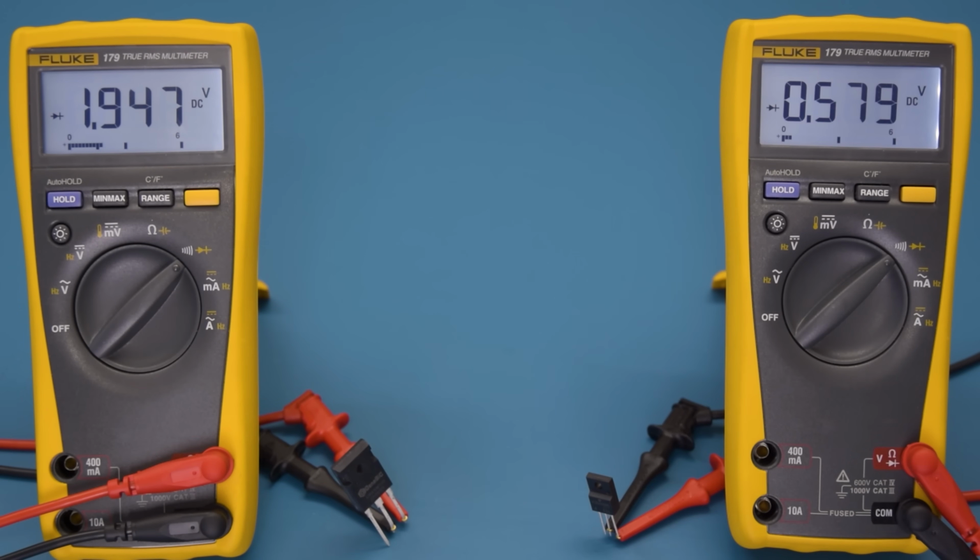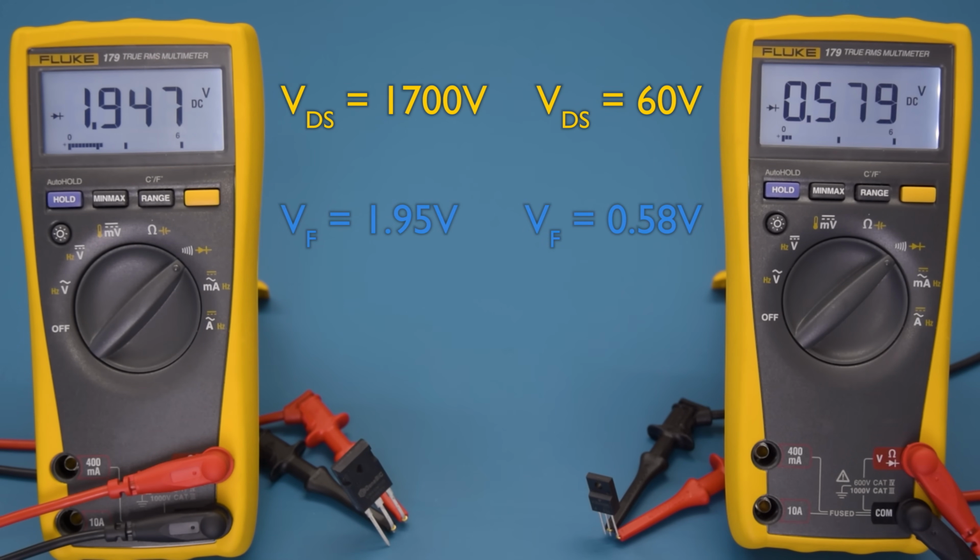Zero voltage switching has more of an impact in higher voltage converters, because the diode forward voltage that's still being switched represents a much lower proportion of the full DC voltage that would otherwise be switched.